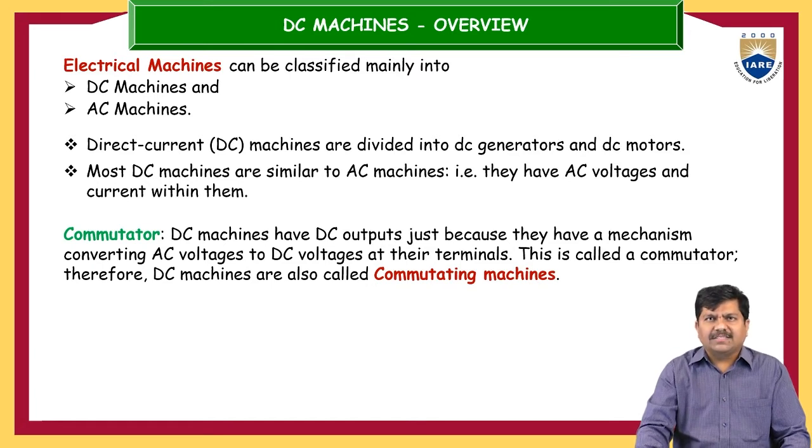So if it is a DC machine, a commutator is mandatory. Otherwise, the energy across the armature will be alternating, and you cannot run DC loads, nor can you call that machine a DC machine. If you are expecting DC power from the machine, the commutator must be connected.